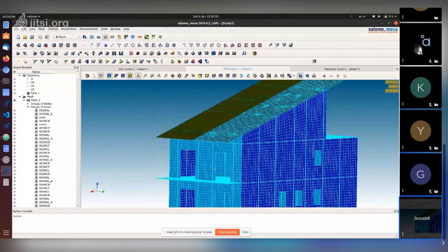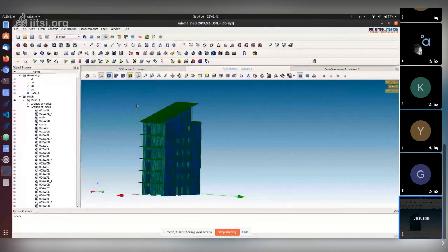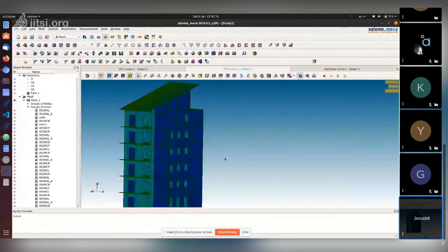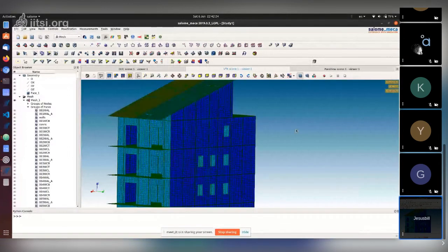So you're saying that certain elements you would mesh a different way, and the program should be able to tie them in from surface to surface quite easily, or do you have some mucking around after, fixing up and touching nodes and stuff like that? Personally, I never touch anything after.